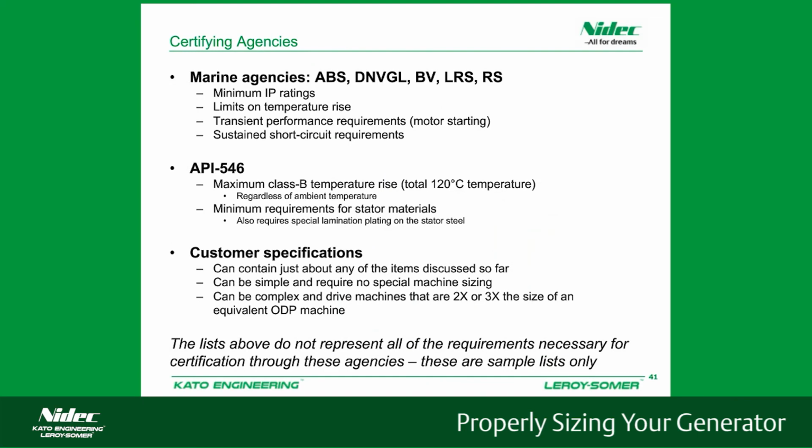So our marine agencies, ABS, DNVGL, BV, LRS, and RS, will often have a minimum IP rating requirement. They will have limits on their temperature rise, and they'll also have transient performance requirements, typically less than a 15% dip at 60% load.